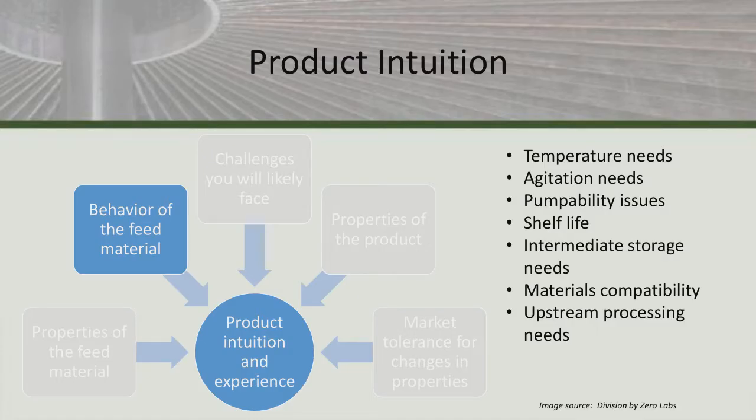Let's talk about the behaviors of the feed material. Is it something that needs to be kept warm before you spray dry it? Do you need high shear agitation to keep it as a homogeneous mixture before it's pumped into the spray dryer? Are there any pumpability issues beyond viscosity changes that we should consider? And what is the shelf life? Do you need to have this spray dried immediately once it's arrived on site, or can it be stored?